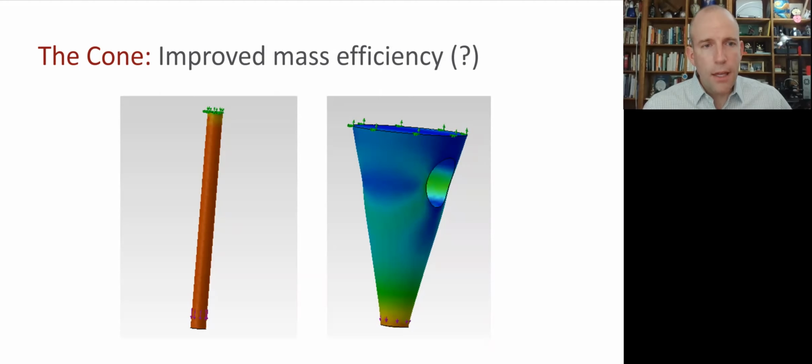So one is to say, all right, the stress is F over A. I want the stress to be uniform. And so I want the cross-sectional area to be uniform. And if I reduce the radius of the top so that matches that at the bottom, I have a rod instead of a cone. And it will turn out that this is a very good approach. Here we see that the pattern of stress is very uniform along the length of this rod. And it's red, and you might first think, oh, that's bad. Red is high stress, but again, we don't have the scale here, and it will turn out that red is some moderate level of stress, and if you pick your radii well, it'll be exactly what you want to achieve your factor of safety.